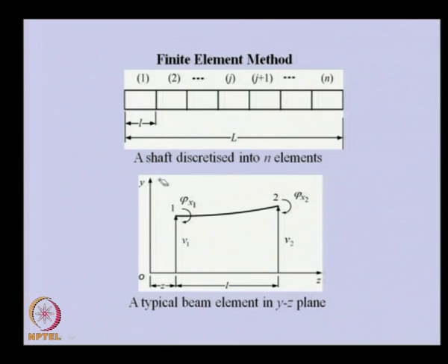As we discussed in the previous lecture, in an Euler-Bernoulli beam, the motion in a single plane is uncoupled with respect to the orthogonal plane motion. So, we can analyze the one plane motion separately, and the other plane motion orthogonal to this will be identical to that. That means the zx plane motion we can analyze on similar lines, because in this particular case element properties are the same in these two planes.